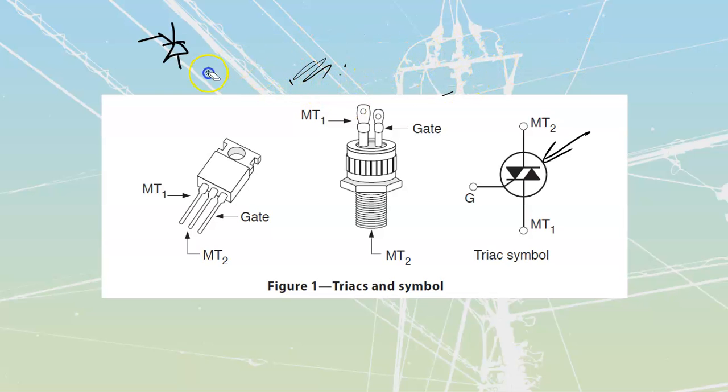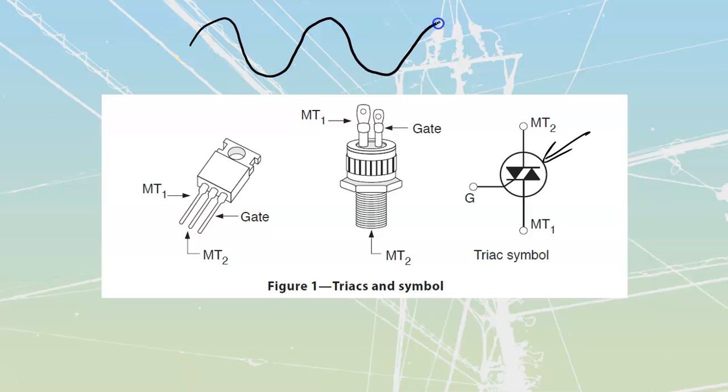The Triac is bidirectional, which means that it passes current through in both directions, which means that any load connected to it is also going to see AC current going through it. And like the SCR, we're going to trigger this thing based off of time. If this is my sine wave over here, we can cut away just a little bit at the front of every single one of these, or we can cut away a little bit further into it to have less power.